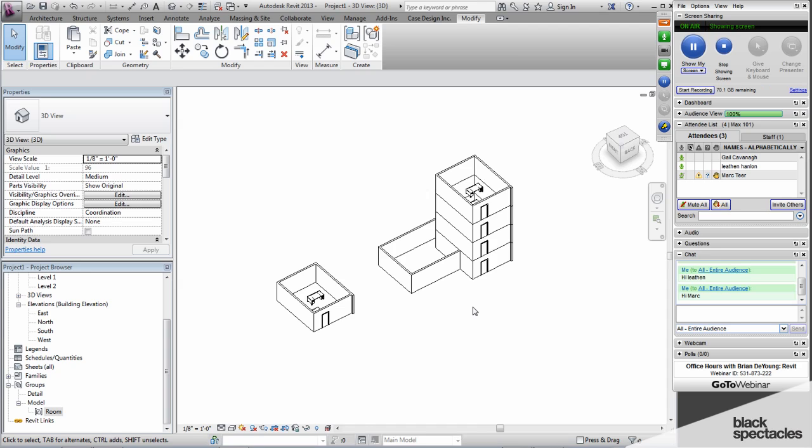Yes, so we will create a file that is literally just the three-dimensional building, nothing else. There are no sheets, no documentation, it's just the model itself. Then we create a whole other file which does not contain any three-dimensional geometry at all. We don't build anything in that model. All we do is link in all the building files so that we can see everything on the entire project: the building, all of our floor plans, sections, elevations, and everything we need to see, but it's all coming from linked sources.